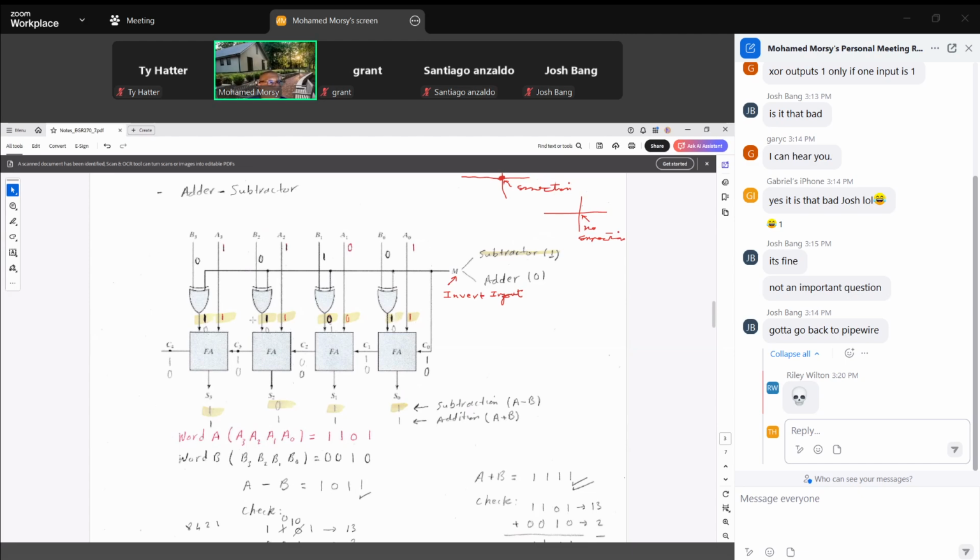We talk about the highlighted inputs and outputs now. So 1, 0 means we have 1 here. 1, 1, we have 0 here. 1, 0, we have 1 here. 1, 0, we have 1 here. So these are the outputs of the exclusive ORs, which represent inputs for the full adder.